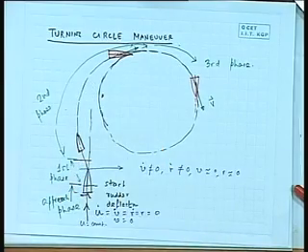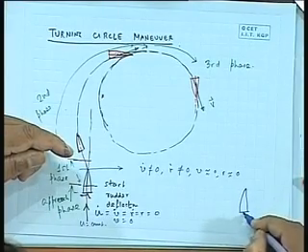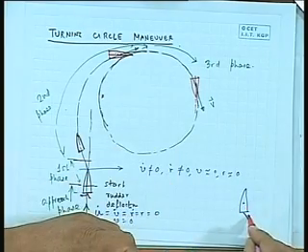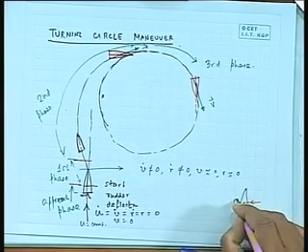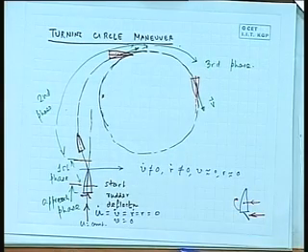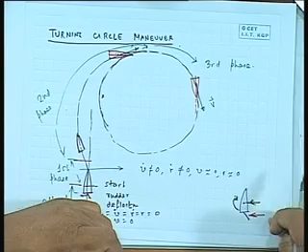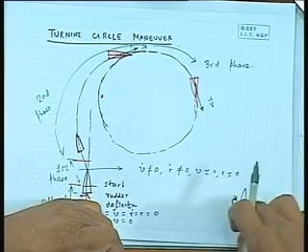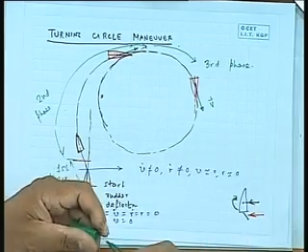Okay. See, now this is the interesting part. When you give a rudder here this way, what happened? This is my CG of the ship. I will get a force this side. This force is going to be equal to this force plus this moment. Okay, or rather with a color if you draw it, I am going to get a force this side. This force is equivalent to as if there is a force through the CG and a turning moment. All right. So the whole ship actually yaws.